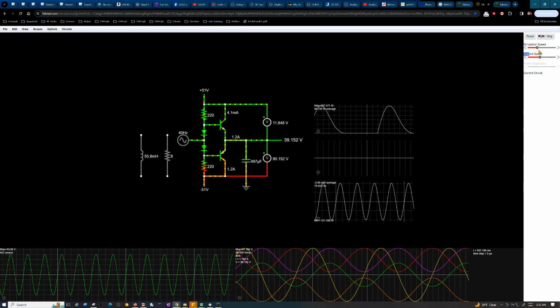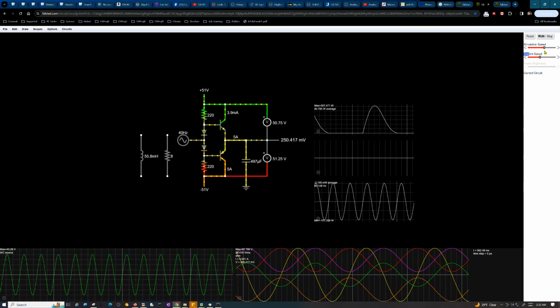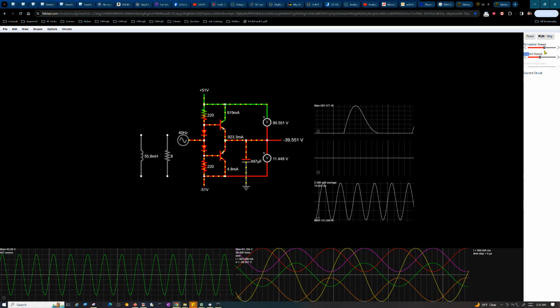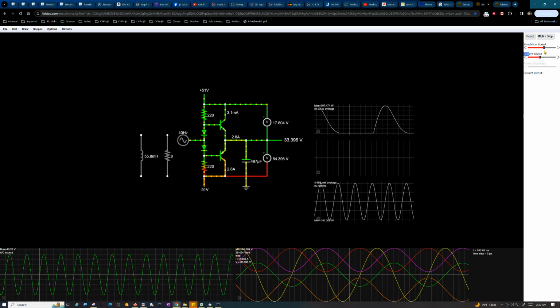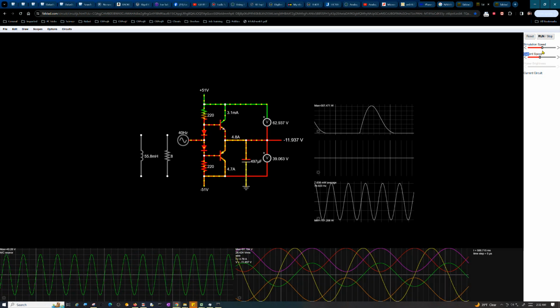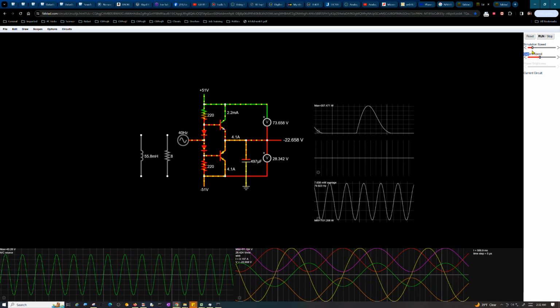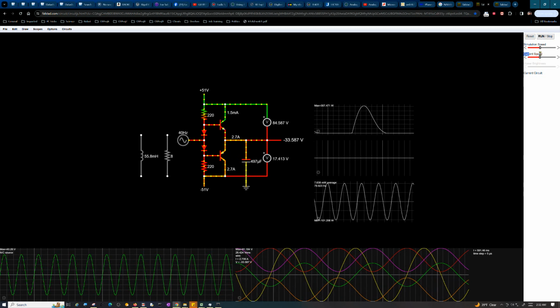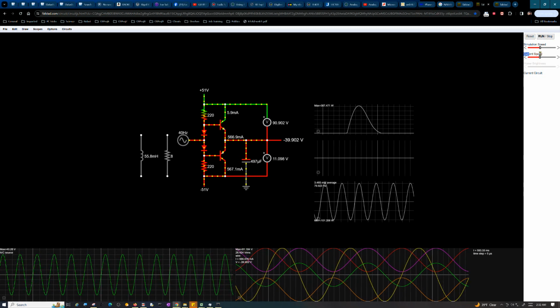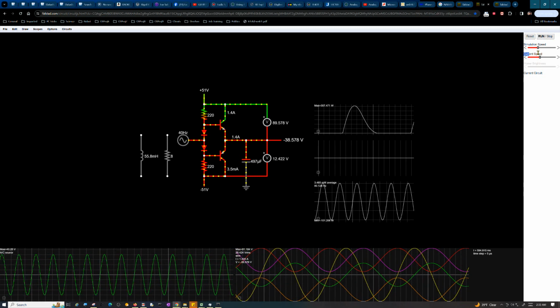Just pay attention to what's going on here. 12, 13, 14, it's up to 90 volts. Now it's falling, and it just never gets down to below about 11 volts. So it's always got 11 volts across it, even when the transistor is fully on. So any current that's going in there is still dissipating power even under those conditions, quite a bit.